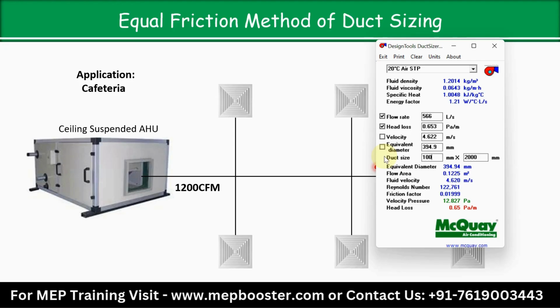Okay, and better is what? Always try to maintain the ratio close to 1:1. Because we know that the aspect ratio of a rectangular duct should ideally stay between 1:1 and 1:4, and designers aim to keep it as close to 1:1 as possible. Why?